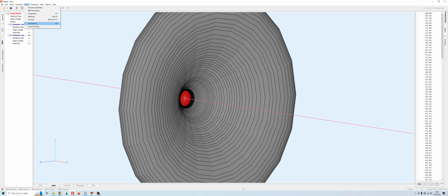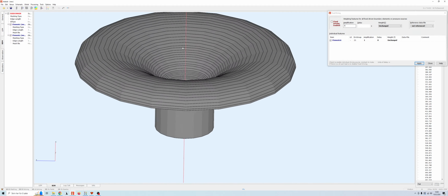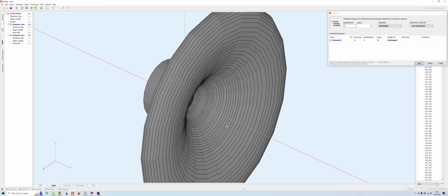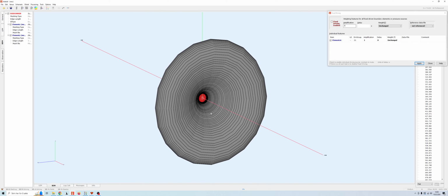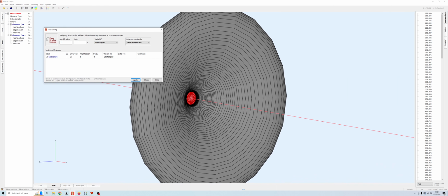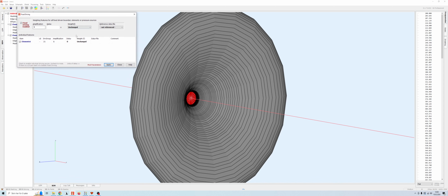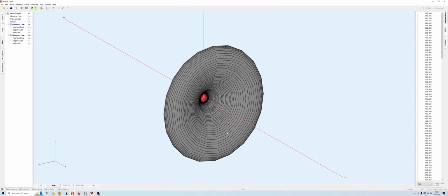And now, once again, we have to go to fixed driving. And this is because, once again, we have no lumped element model coupled to this driven element. And so for it to radiate any sound at all, we have to choose fixed driving. In this case, I'm once again going to choose, just like in the 2D room tutorial, fixed driving enabled and then divide by jω. Click apply, and then we can close. Now everything is ready, more or less.